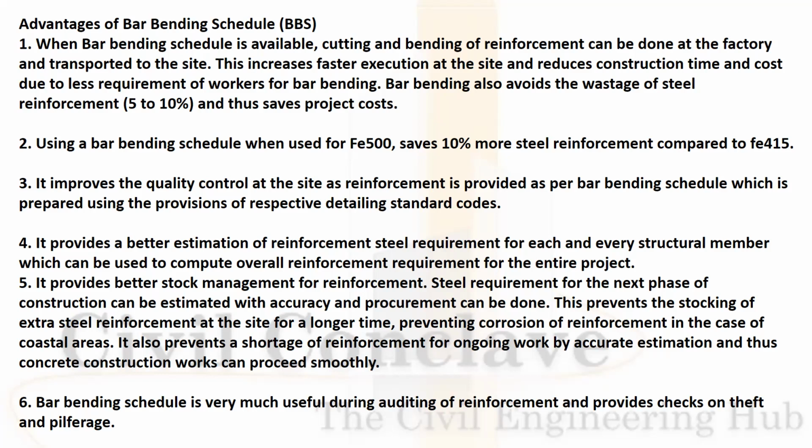It provides better stock management for reinforcement. Steel requirement for the next phases of construction can be estimated accurately and procurement can be done. This prevents excess stacking of the reinforcement at the site for a longer time, preventing corrosion of the reinforcement in case of coastal areas.